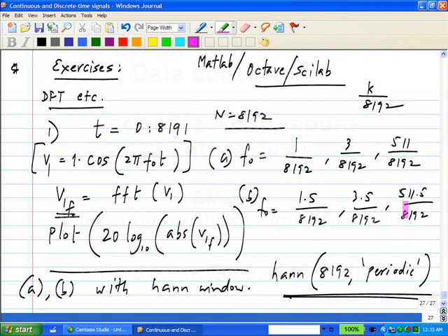This is already on the pin, on the FFT pin at the good frequencies. But still you will see some leakage because of the Hann window. Right? At 2 points you will certainly see a leakage. But you will see which is better for what. Okay, whether Hann window is good for this or that. And so on. Okay? Is this clear? So please try it out.